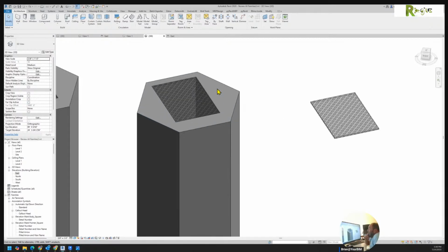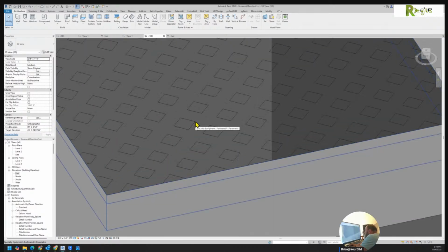Okay. Now, what I had covered earlier is this was extremely frustrating creating this pattern because I was trying to create the smallest pattern that Revit could make. And I spent, a matter of fact, I did a stream on it explaining my conversation with chat about how small was the smallest line I could have in a pattern. So in other words, when I bring a pattern in, a model pattern in, and I shrink it down to the point that one of the shortest lines in that pattern, if this is a wood pattern, it's going to be the smallest little line segment. It can only be at 3/8 of an inch. And then it starts to fail.